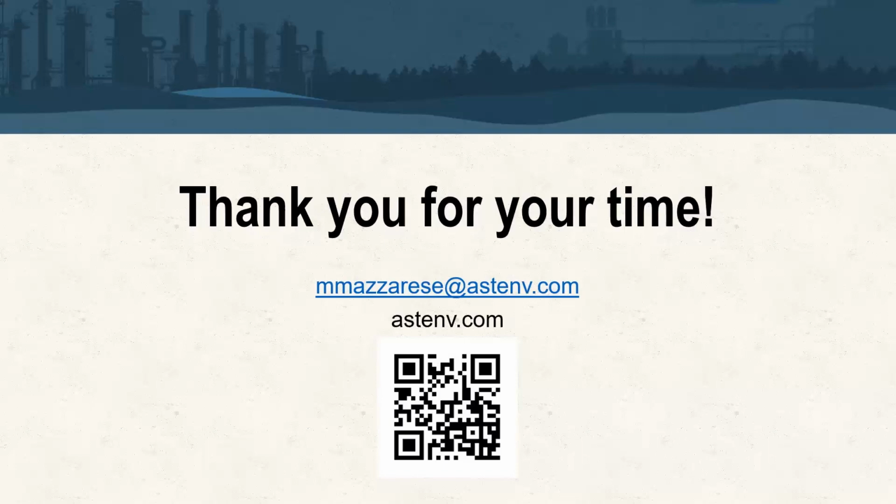AST is working with Setco to inject their Fluorosorb technology. If it was a commingled site that had PFAS, we would probably look at using a combination of trap and treat technologies with something like Fluorosorb, that we feel is a better adsorbent than activated carbon. To go back to the other commingled sites, if you've got things besides chlorinated ethenes, such as ethanes, methanes, chlorobenzenes, or even petroleum hydrocarbons, we've had sites with all of those, or a combination of them.